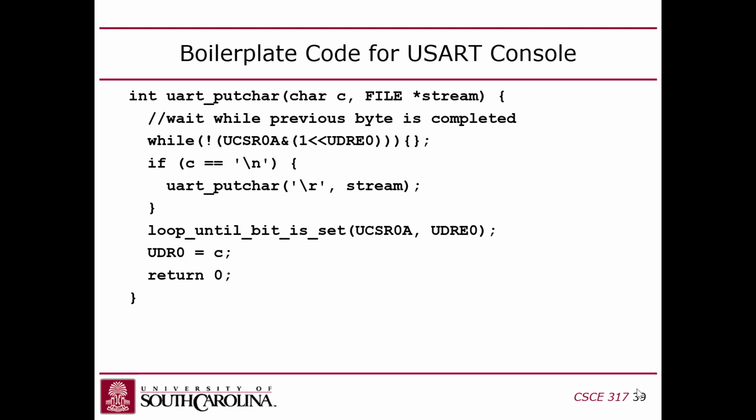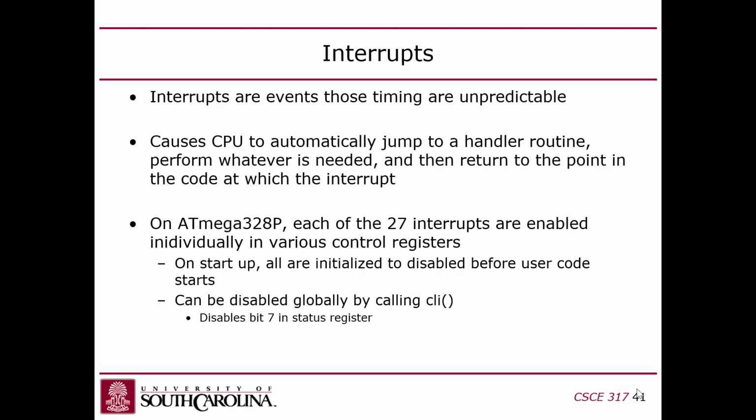So the other way to handle this is to use an interrupt, which allows you to do whatever you want to do. You can do other stuff on the chip. The chip can do other stuff, and then whenever the UART interface is ready to send its next character, it can interrupt the software. The software in the interrupt service routine can send the next character out, and then it can resume what it was doing. So that's an example. You can have an interrupt for that.